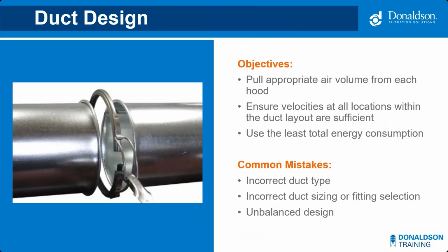Again, a few common mistakes that we see when it comes to duct design is the incorrect type of ducting is being used, the incorrect duct size or fitting is being used, and the duct system is not balanced correctly.